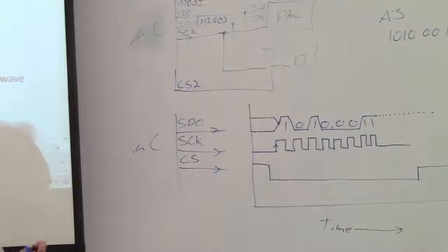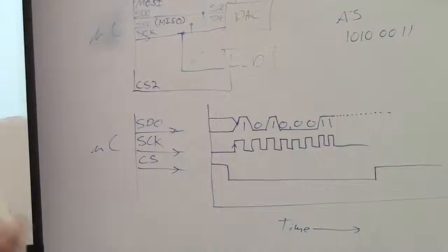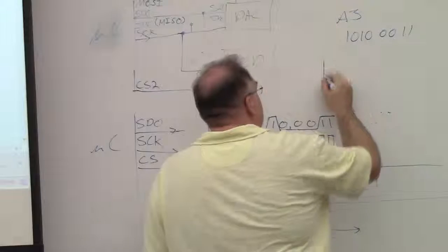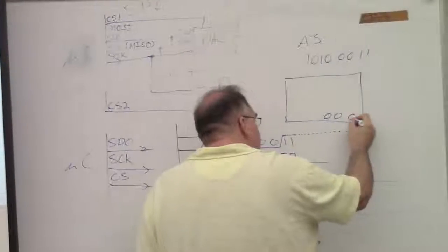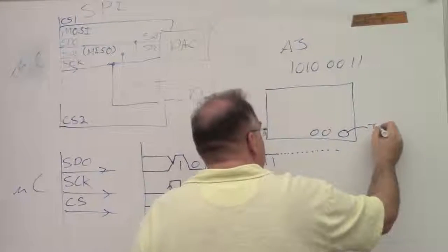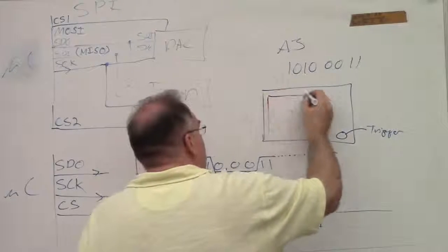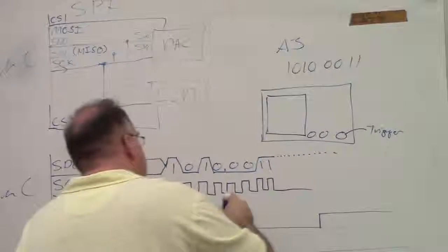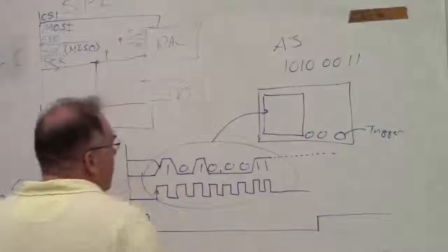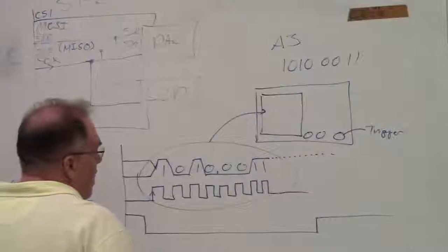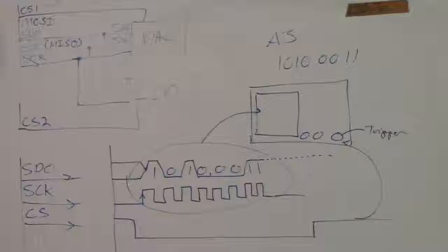Now, there is a problem with our oscilloscopes. It's not a horrible problem, but we only have 2 channels. But conveniently we have a third input that's called the trigger input. So what we'll be able to do is graph these 2 signals on the graticule, but the trigger will have to go from the chip select, and you won't be able to see it.